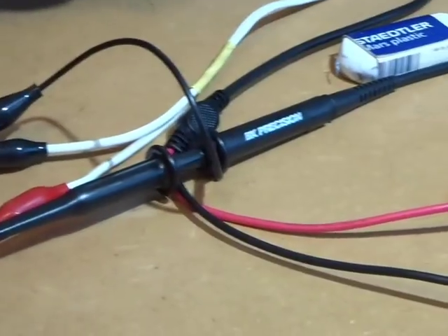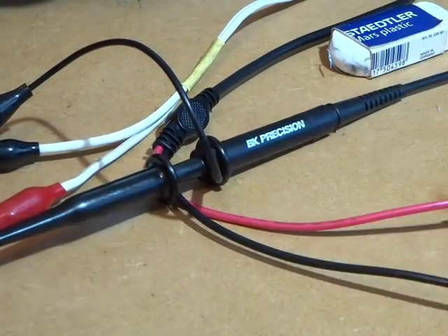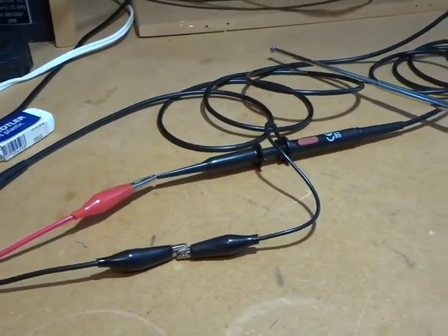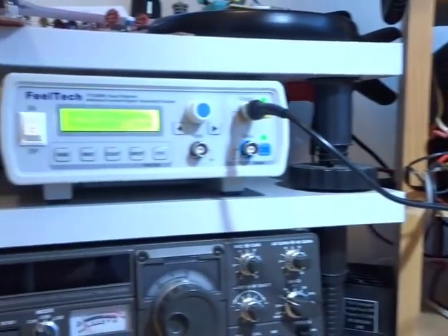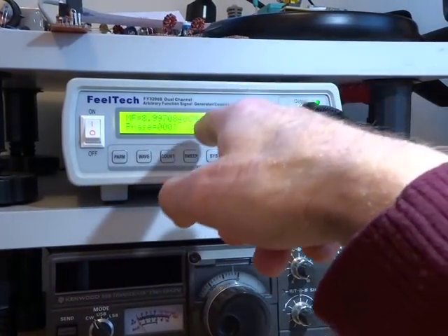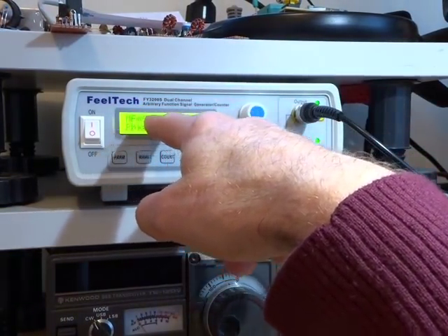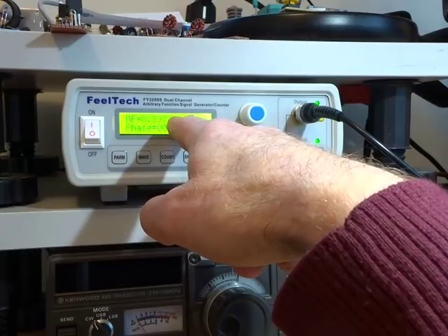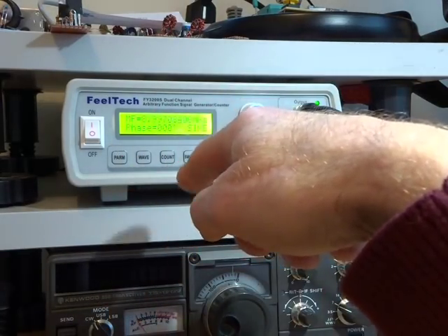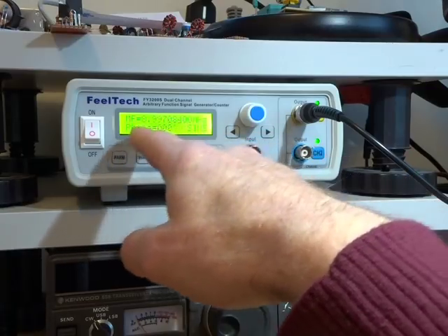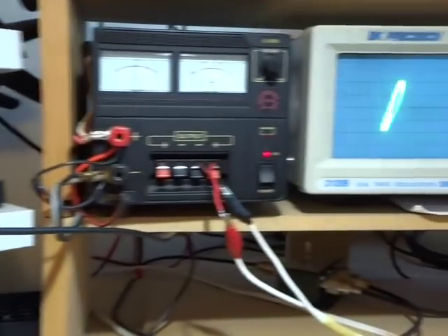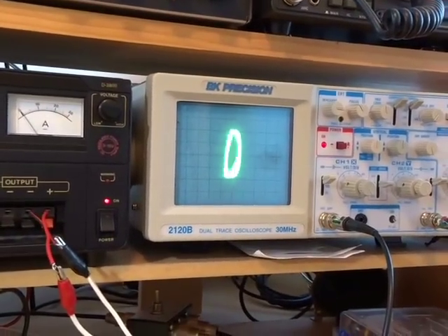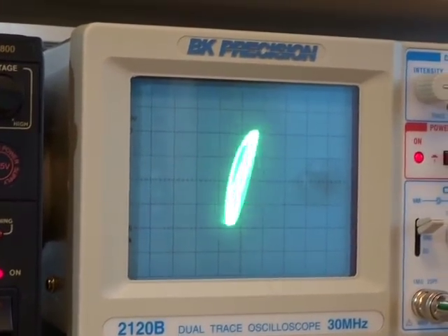I've got the probes on times 10, so just trying to minimize the loading on that particular oscillator, and feeding that into the oscilloscope. Now the second input I'm taking from the SIGGEN, and I'm going to tune the signal generator to be close to, and we'll look at what the effect's going to be to the frequency that's coming out of the signal generator. So sine wave, and I've adjusted the amplitude to give me the same amplitude as what's coming out through channel 1.